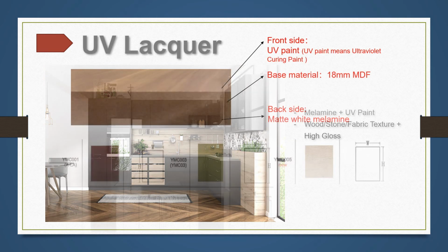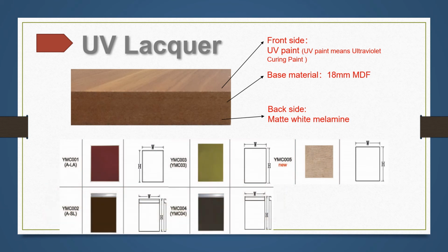Usually, we have painted doors in pure color and high glossiness, and we have melamine doors with various colors and grain with little glossiness. UV lacquer combines them and gets special effects. I would like to call it high gloss melamines. The UV lacquer itself is a special transparent lacquer that can be cured really fast under ultraviolets.